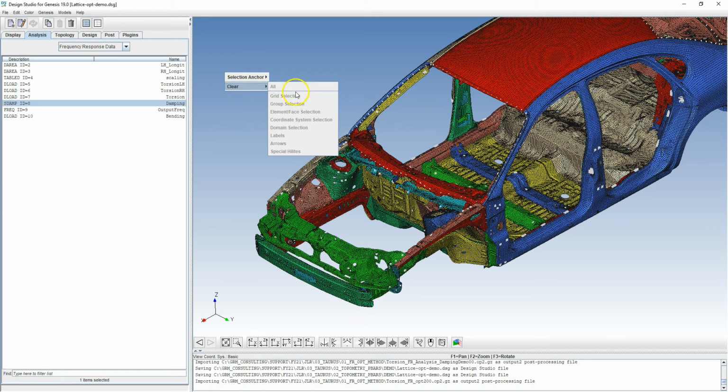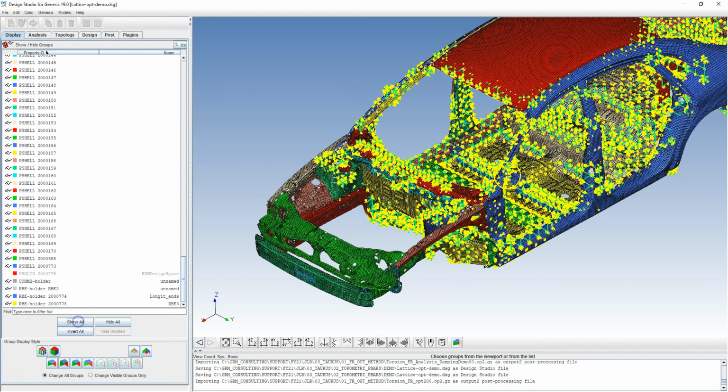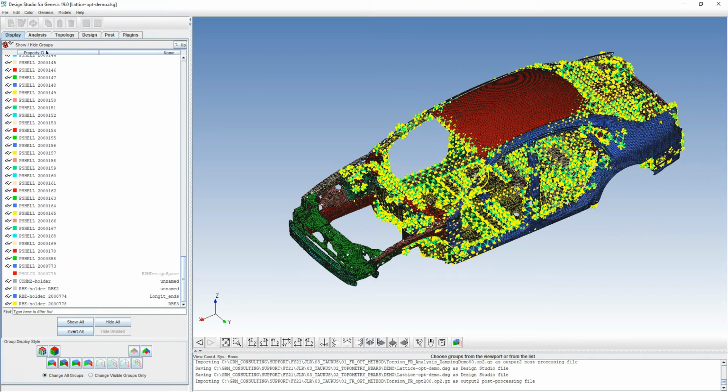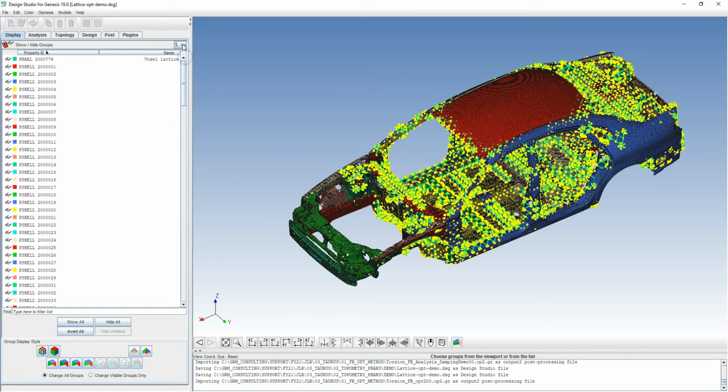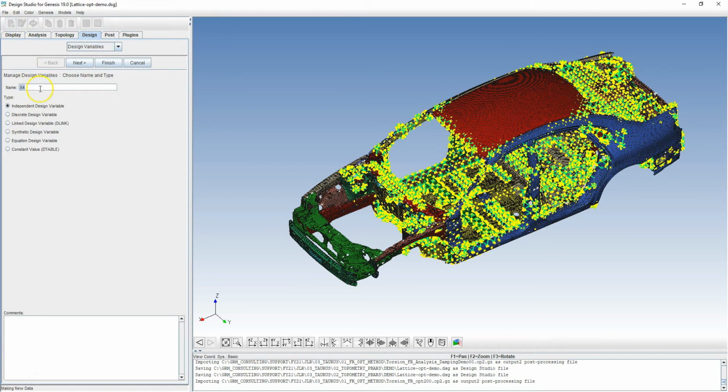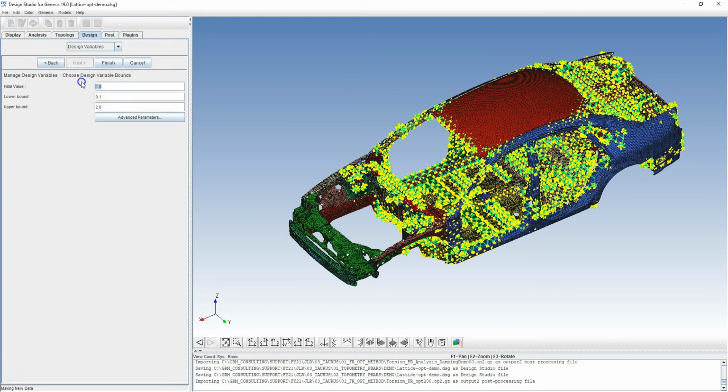Okay, so let's take a look at the design data now. If I put everything back on screen, we want to optimize the diameter and thickness of each of these beams. We want to do so independently, so each beam is considered on its own. So we can do that using topometry optimization inside Genesis. To set it up, first of all, we just need to create our design variables. So I'll create one for diameter. And here we're going to start with an initial diameter of 50, a minimum of 0.1, and a maximum of 100.